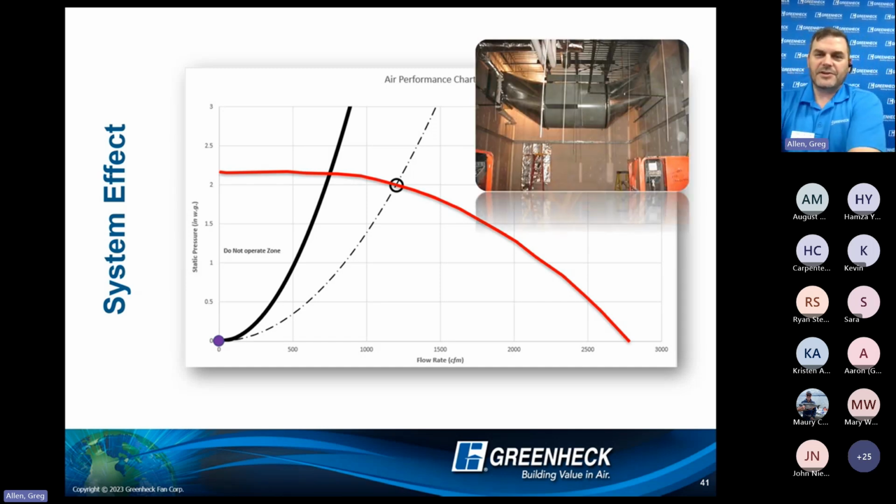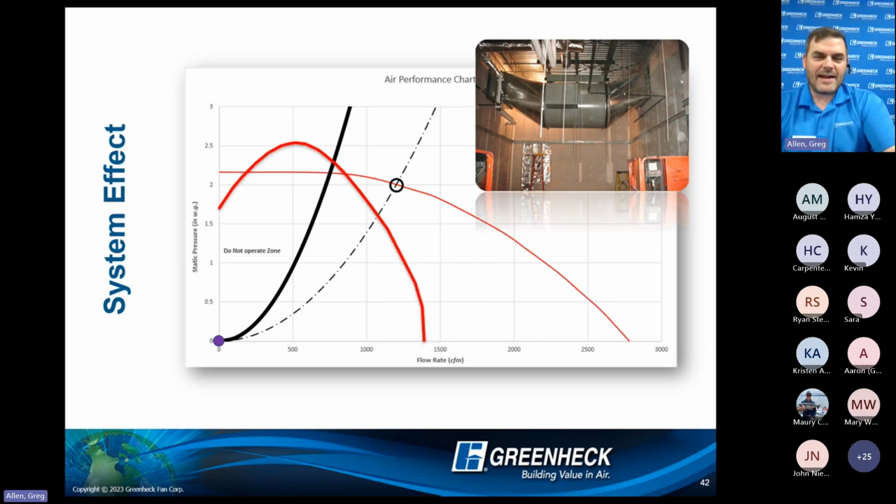But this is the installation we're going to have today, right? I have this fan where I am actually expanding and coming in at an angle. And then on the outlet, I'm restricting and at another angle. That does not look like how I tested this fan. And in this fan curve, let's make it a little alive here, it actually does not even look the same anymore. It looks completely different. And the point that I impact between my system resistance and my new fan curve is going to show quite a loss of CFM.